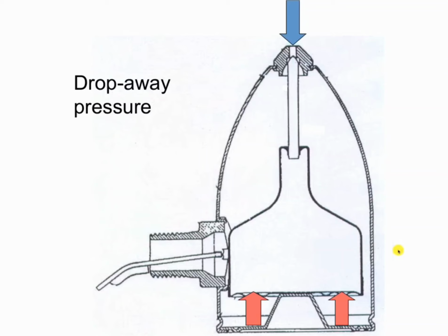For instance, first of all, I've been inside New York City Housing Authority buildings, and these are residential buildings, so I'm assuming he's talking about a residential building. The system that he's describing is a single pipe steam system, and these are open systems, which I have never seen in a New York City Housing Authority building. From what I've seen, these are run off of a vacuum system. Anybody know about a vacuum system? That is a 2-pipe closed system. There are no air vents on the radiators. I'm not saying that what he's saying isn't true.